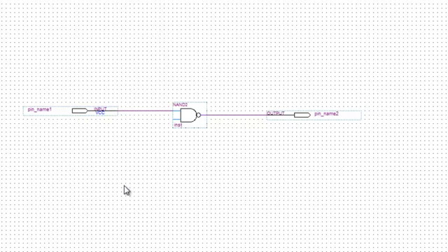There you go. You've just drawn your first two wires. Now I'm going to make a connection here. I'm going to start drawing by holding the left mouse button and come up here, and you'll see it'll make a little square, and when I let go you'll see that there's a dot here now. That means that those two wires are connected together.